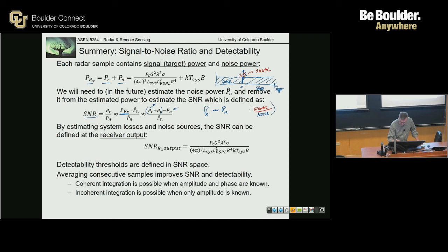All right, so it's integrated power then. It's the integrated power. But for a single pulse, how would you detect it? In the noise floor. Yeah. So for a single pulse, the signal power from a single pulse relative to the noise will always be positive. If it's below the noise or within the noise, then you're just calculating noise values. This could be, yeah, could be negative.